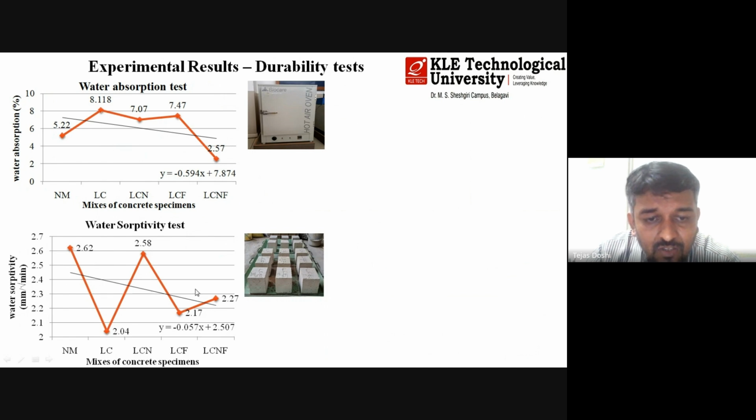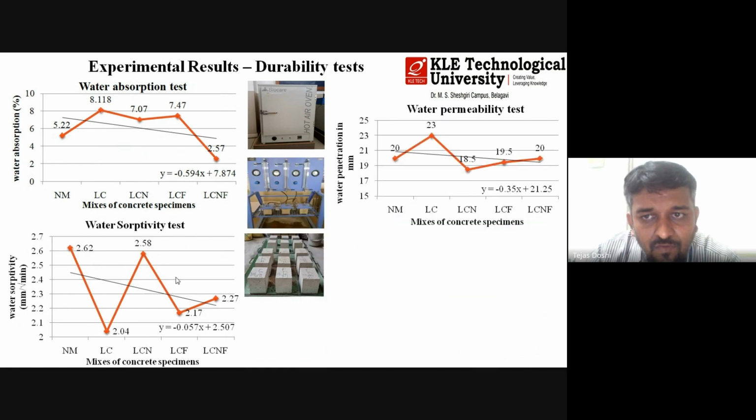The trend is almost the same when seen with respect to water absorption, but it slightly increases for LCN, where it is LC3 concrete with nanomaterial, because of the porous nature of concrete. Then we have the water permeability test. It is observed that the LC3 concrete also falls within the acceptable range for water penetration depth.